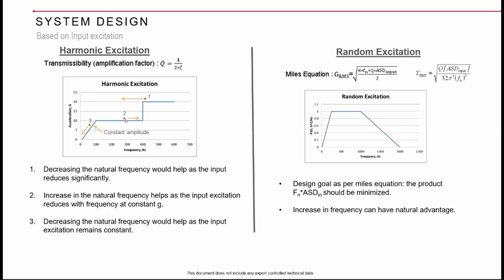I cannot go and reduce the frequency so much that I can enter somewhere here. And you have to be careful that it is a harmonic excitation. So acceleration is equal to omega square x. When I say omega square x here, always in case of vibration, we have to see the responses in terms of displacement. So x is nothing but acceleration by omega square.